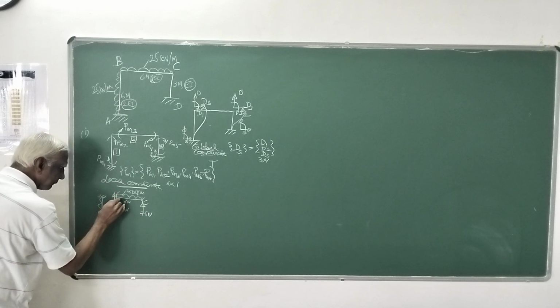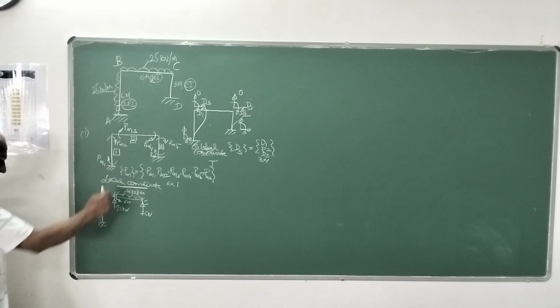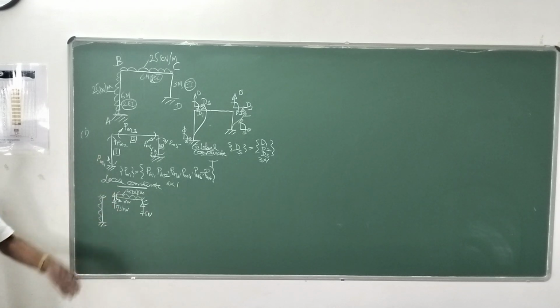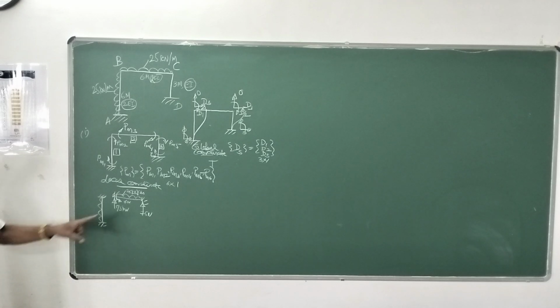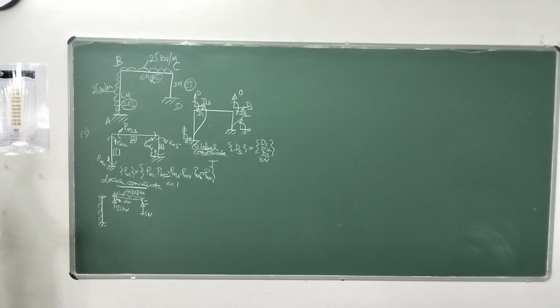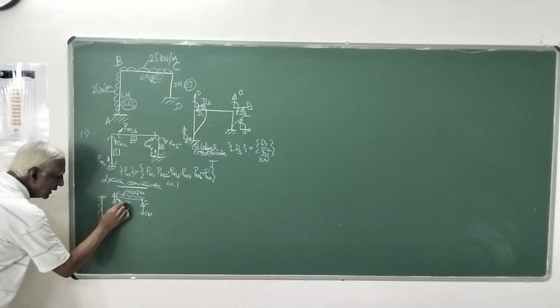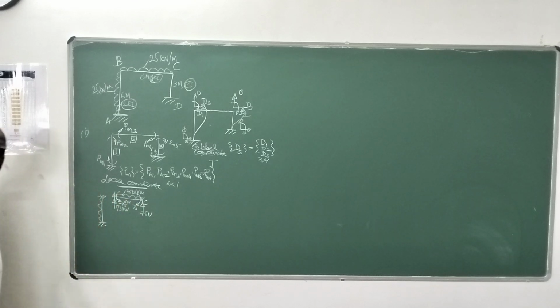And the moment here is in the anti-clockwise direction, because applied moment due to load is clockwise, resisting has to be anti-clockwise. So this moment will be Wl squared by 12, where W is the intensity of the load. So that is 25 into 6 squared by 12, that is also 75. Since the resisting is anti-clockwise, as per our notation, it is minus 75. So here it is plus 75. On the same lines for this also.